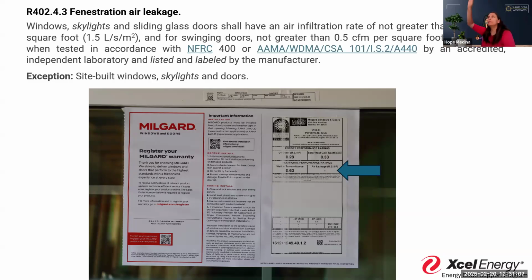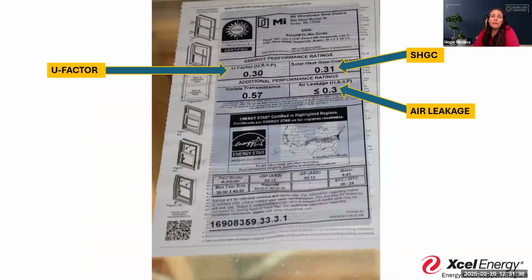Like sunglasses, you have that coating on the window that is darker. So those windows were darker. And in having those windows darker to meet those requirements, we also have building code requirements that say we have to have so much natural lighting come in. So we had to ensure that we weren't impeding that. That's the visible transmittance concept.